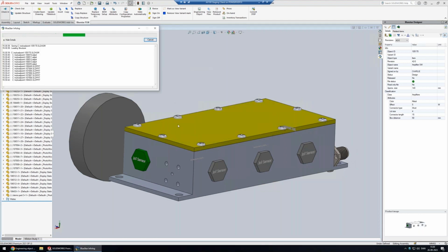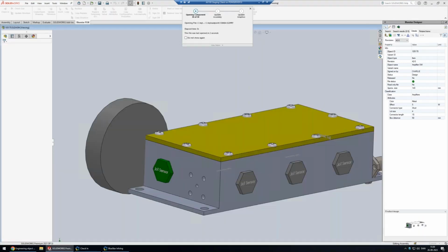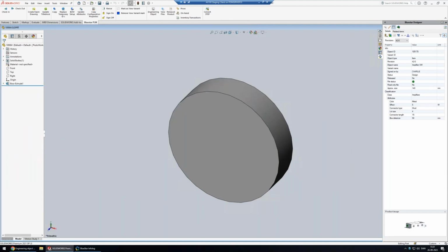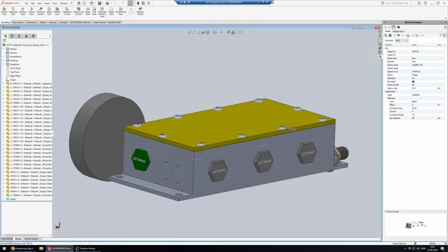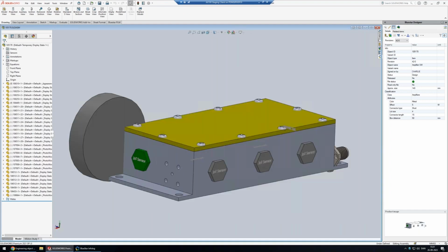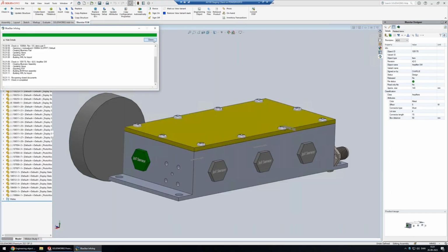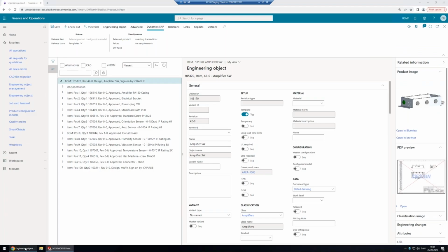to get the PDF updated, to get the bill of material updated, and the check-in will also recognize that you have a new component. I will run in silent mode, which means that it will give it the next new number. It will rename the file to the item number. It will fill out the title block information, and it will update the bill of material, the drawing on this amplifier that we have. So now we have stored the data from CAD into Bluestar.